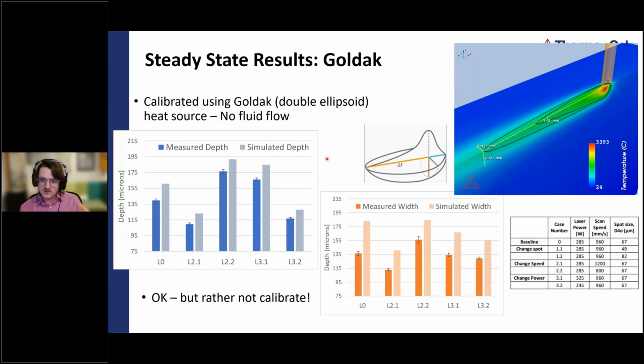So the way to capture the effects is to use the so-called Goldak or double ellipsoid heat source. If you just apply a Gaussian heat source, which the laser is, right? Or depending on your beam shape, I guess, but it's just a Gaussian heat source. If you wanted to simulate a keyhole, or if a keyhole actually happens, you would not capture that accurately. So Goldak, in their paper, came up with this double ellipsoid heat source. The heat source is volumetric, so heat is applied subsurface, which helps account for the keyhole.